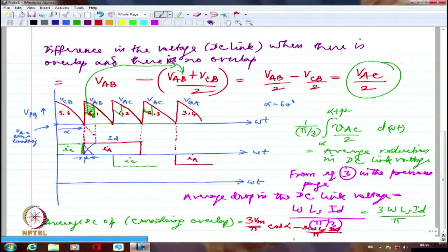And you are reducing that abrupt rise and fall by having an inductance. You didn't put the inductance, it is there in the system. So that causes the current to rise and fall in a slower fashion, and the current becomes a little bit more rounded. Because the current becomes smoother and rounded, the harmonic content in the current comes down. So it is closer to the fundamental or sinusoid. This is another effect, a corollary of the current having become smoother.